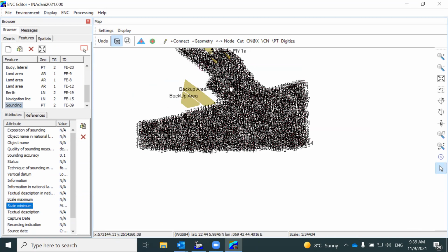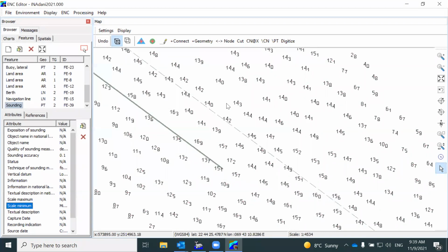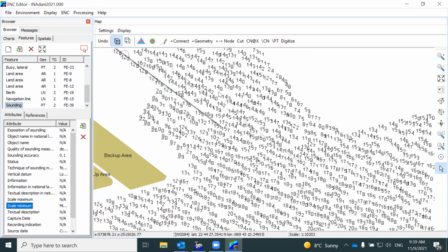So that's the soundings. You cannot edit individual points now because that's the same feature actually. So there is no possibility to change individual sounding, individual depth, no. So you need to clean your soundings and sort them out, of course, before you import these soundings into S57 chart. Now it's a feature here. You cannot do anything here. You cannot cut it. You cannot move the spatials. You cannot edit the label. You cannot edit the depth here. No, it's done. You can delete all the feature. Remove feature.